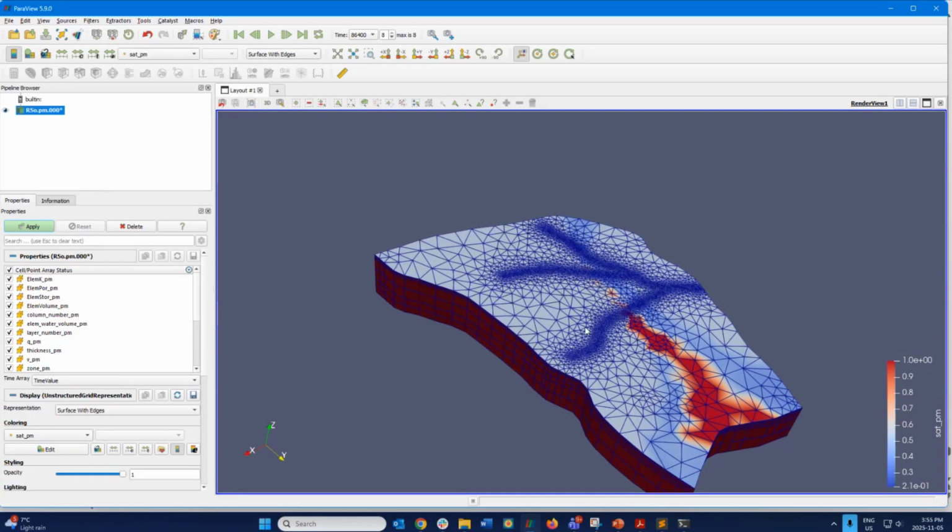So these mesh elements are also quite small, but at catchment scale, what does that really even mean? Some catchments are 2,000 square kilometers. Other catchments are 50,000 square kilometers. What I will say is this: as your model size grows, you are still going to be limited by the computational capacity of your workstation. As I mentioned earlier, as a new user, I recommend that you try to limit yourself to 1 million nodes max, far lower if you can, and to take a really staged, step-by-step approach.